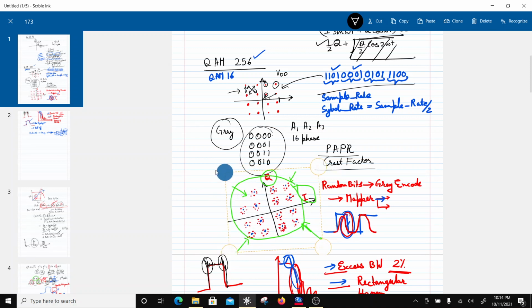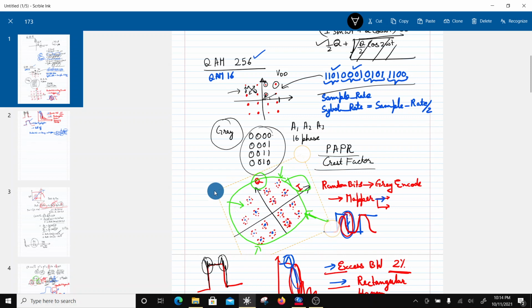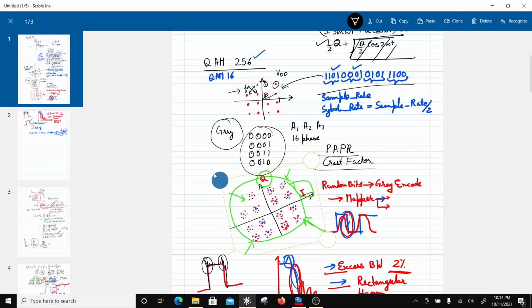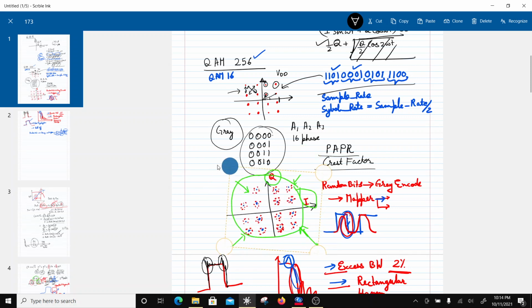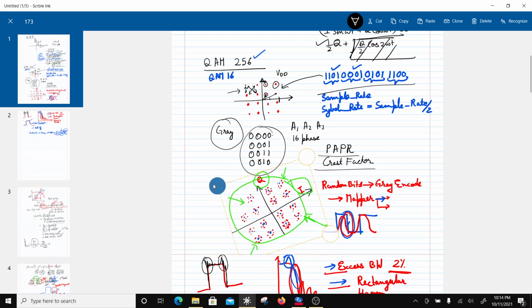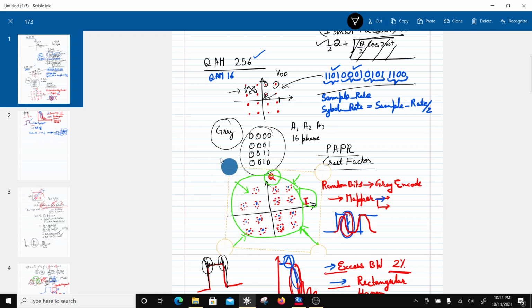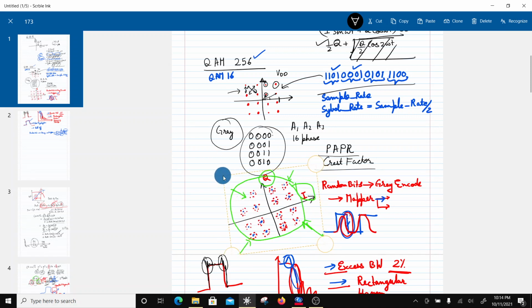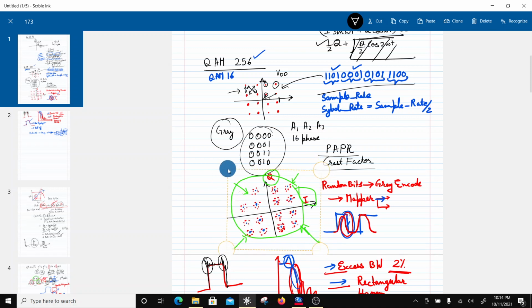So if something is deterministic, then you can reverse its effect. But something like phase noise of a PLL, this constellation starts dancing, and if you cannot predict its dancing, you cannot recover your bits. So phase noise becomes very important, and you can see this dancing once I show you with the phase noise what is going to happen.